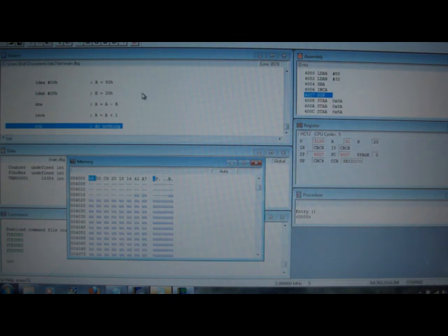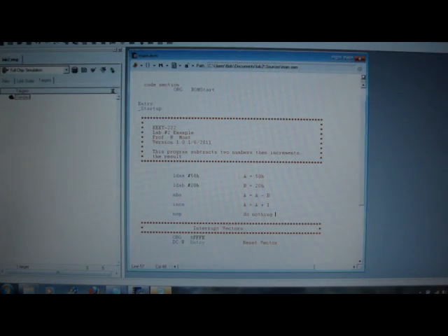And you notice that as we step through, this blue line over here in the top left went down one line as we proceeded to debug or single step the program. That's a huge help in understanding what actually happens. So I advise you to single step and predict what's going to happen so that you can understand what your program is doing. This concludes showing the simulation. If you have errors in your program, you'd have to go back through, and we'll close this window, fix the errors here in the assembly language, and then simulate once again.